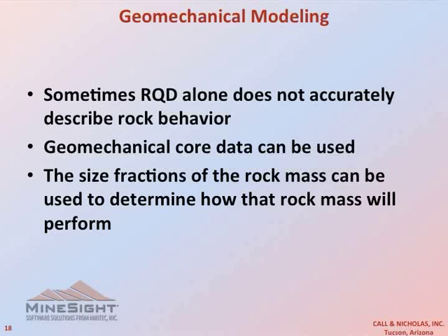we can then also do some modeling with that data. So in a case where there is very low RQD, well, is that very low RQD? What does it mean? What is the size of that material? Is it below an inch, below a half inch? We don't know. By collecting all that additional geomechanical data, we can use that in some of the modeling of the deposit.